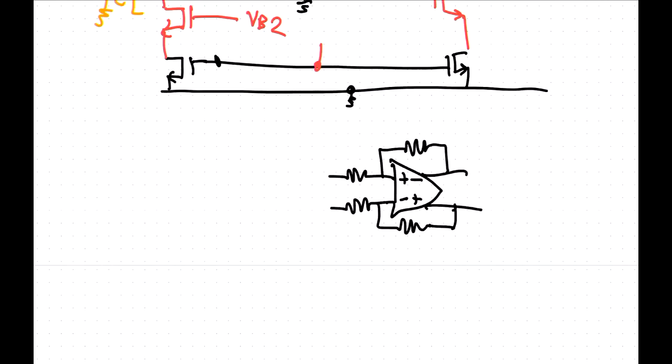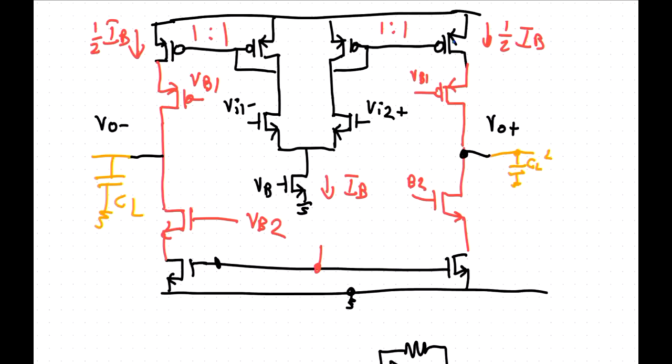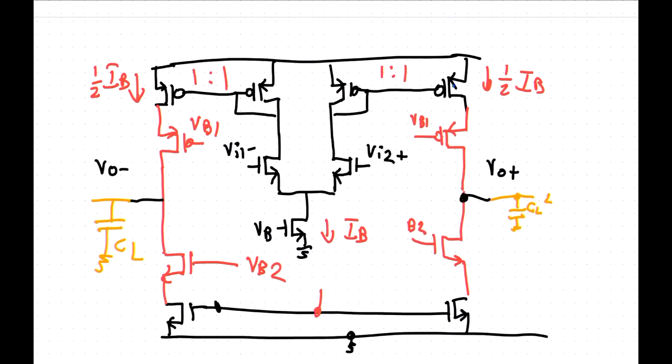And if there is a difference in this current source and that current source, then the common mode is going to be probably sitting right at a negative supply, or at the positive supply. And it's not sitting right in the middle to work properly. So the way that you normally address this is to have another feedback loop that looks at the common mode signals, and you feed back the common mode signals and make sure that the common mode is then sitting in the right spot.